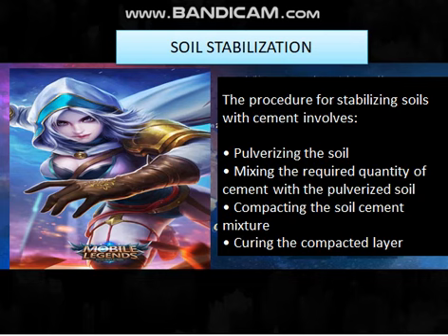The procedure for stabilizing soil with cement involves first pulverizing the soil. For the soil to be stabilized, guys, the soil should be pulverized thoroughly to facilitate the mixing of the cement and soil. When the existing materials on the roadway are to be used, the roadway is scarified to the required depth using a scarifier attached to a grader.